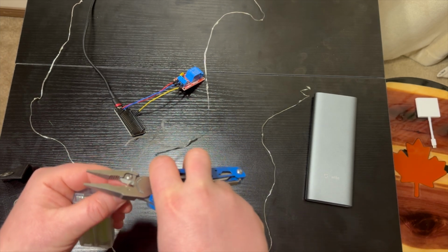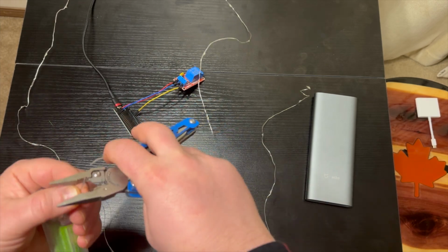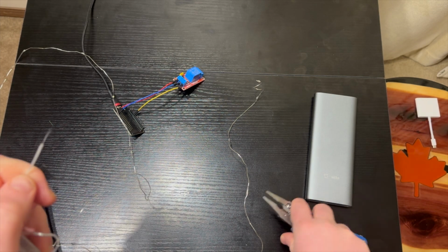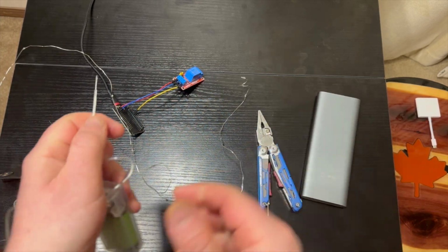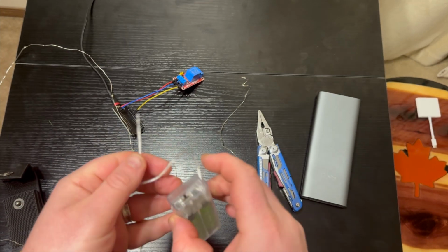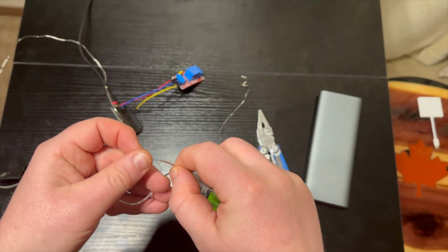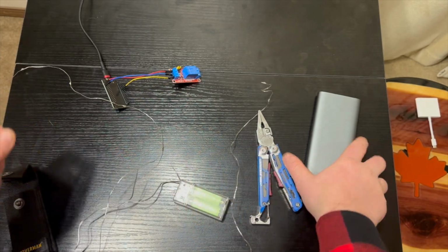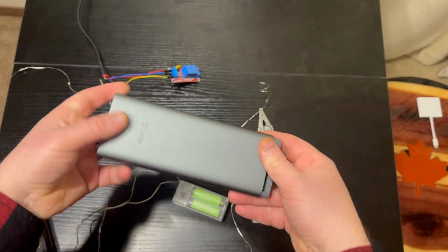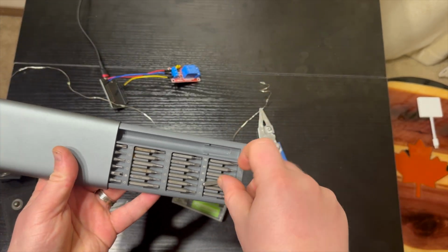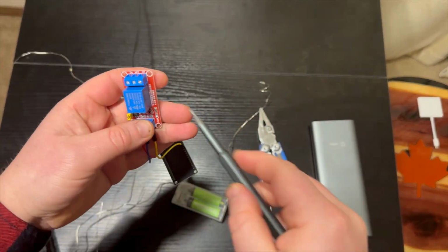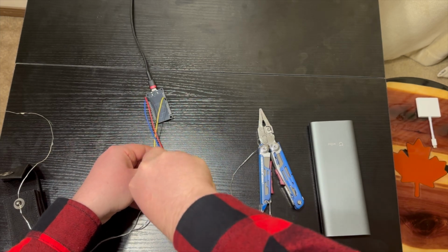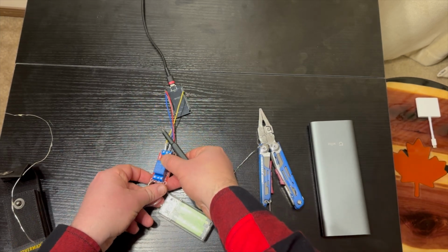I need to clear it from the insulator. Now I will enable the control block and connect two wires. It's time to put wires into the relay. I will connect wires to the common channel and the normal open channel, NO. It means that the lights will remain disabled until the relay enables it.